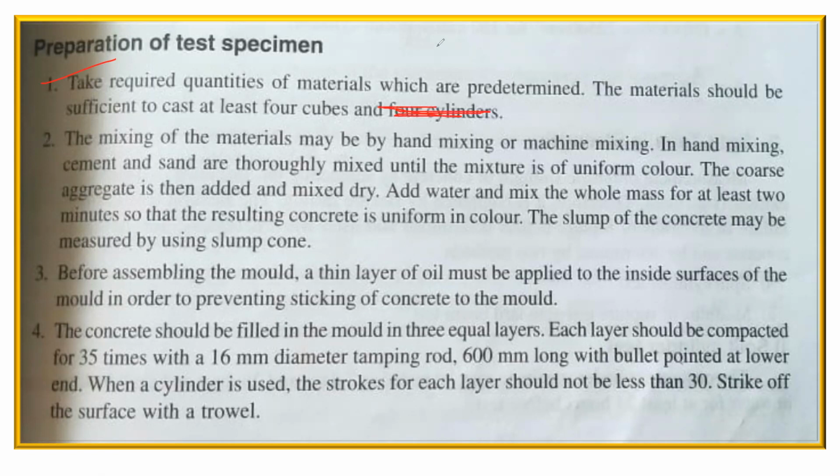First, we have to decide what grade of concrete you're going to prepare. Let us say I'm preparing an M25 grade. Now, why this M25 only? Why I'm not taking M20? We'll come to that a bit later once we finish this. There's a big theory behind that, right? So this is done. Based on that, you try to identify how much cement, how much coarse aggregate, how much fine aggregate is required. With the help of that, you prepare a concrete and you cast the cube.